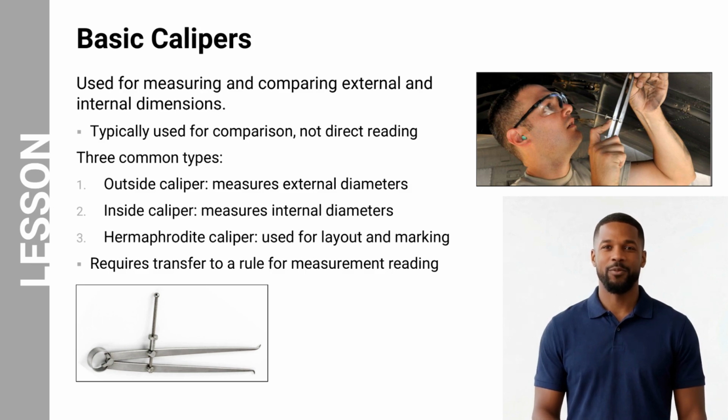Starting with the simplest tools, basic calipers are used to measure and compare internal and external dimensions. Unlike slide calipers, they do not provide direct readings and must be transferred to a scale or rule for measurement interpretation. Outside calipers measure external diameters, while inside calipers are used for internal dimensions.